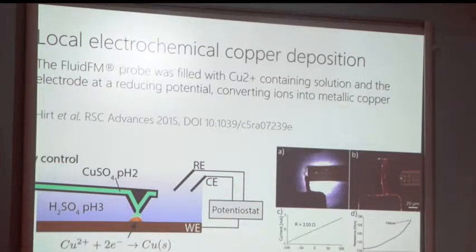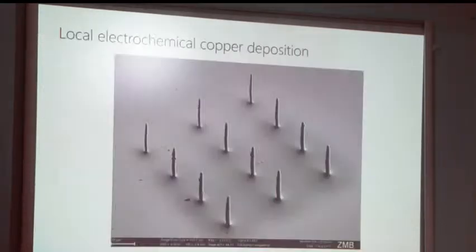Let's say this is an electrochemical deposition process. You keep your sample at the potential where material normally gets deposited. Then you push the liquid through this cantilever hole and drop it wherever you want, and it will get deposited, producing structures as per your choice. For example, some people have made vertical nanowires, seen here in SEM. Wherever they want, they can make vertical nanowires by manipulating on the substrate.